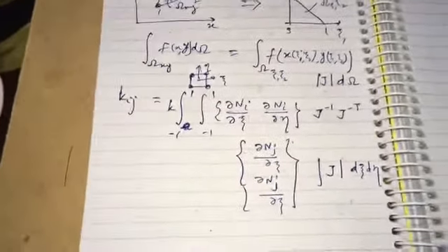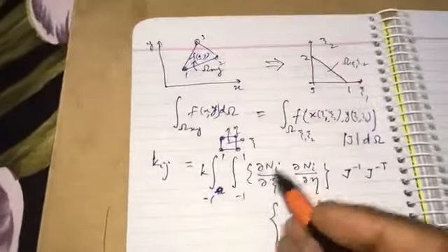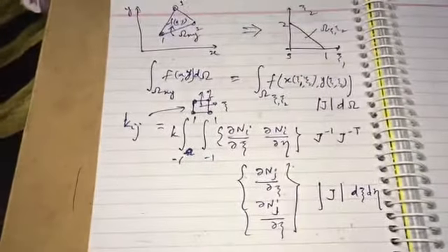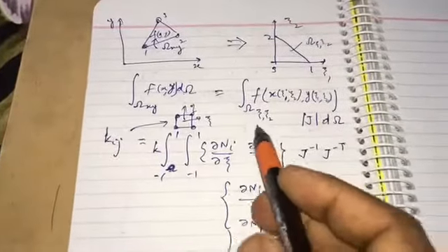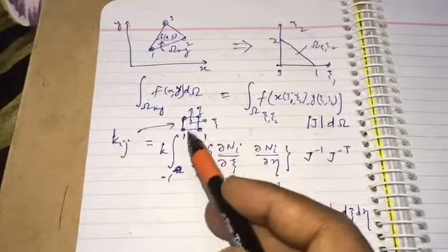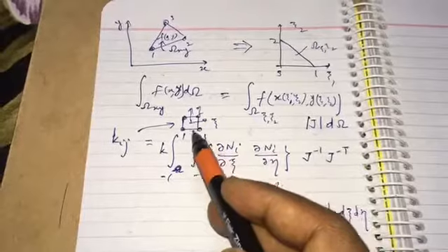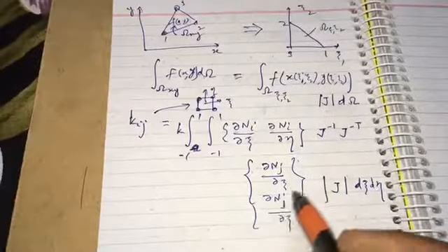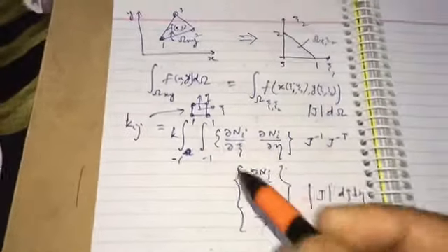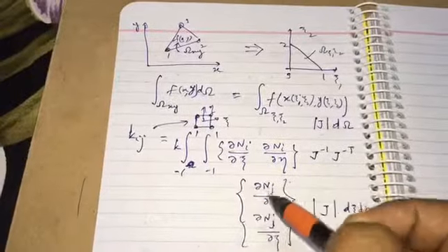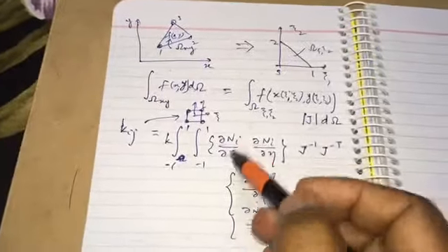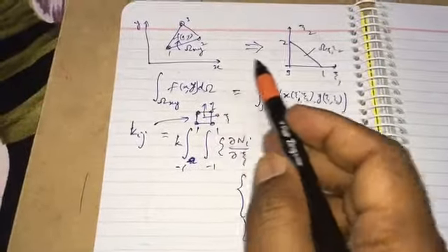So this is what we had for the four noded quadrilateral element. When it is transformed to the xi and eta coordinate system, the transformed area becomes a square. That Kij we calculated in the last lecture video, and the same thing I have written here. How we derived it can be repeated to derive Kij in this coordinate system.